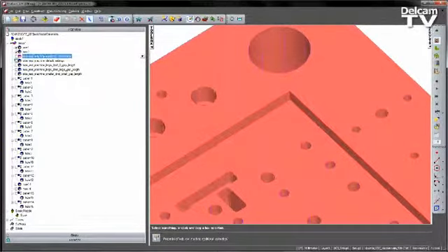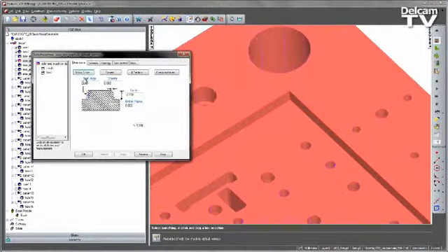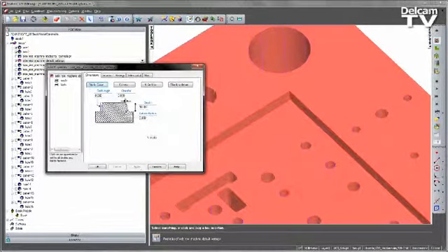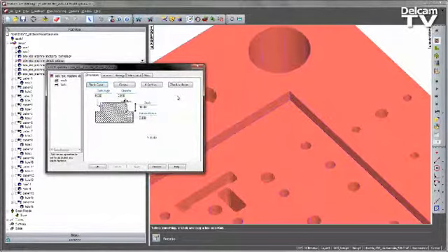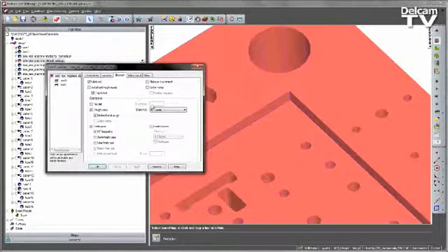So I'm going to turn off the traditional technology toolpath and just look at this next operation. Here you can see in this feature under the stock curve we specified we want to compute the stock boundary from the stock model. We're using the stock model that we created and we're referencing the last operation that was added to it. Under the strategy page you can see we're using NT spiral for the roughing, and we've also checked the option for NT toolpaths for the finishing.